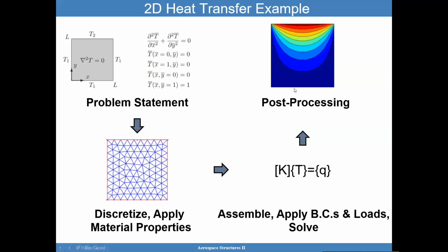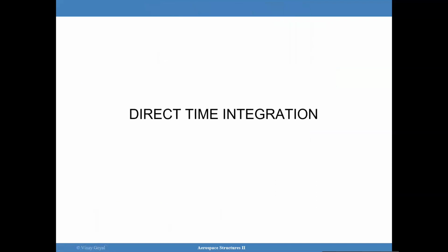So what finite elements has done for you is found a systematic method of turning any partial differential equation into a linear algebra type problem, which allows you to solve for the unknowns, and which allows you to solve for the variable of interest in a simple way. And that is easy for you to even visualize. So let's step into direct time integration. That is the topic that I want to hit next, and I'm going to start talking about dynamics now.